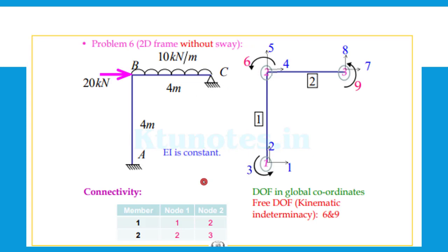Okay, so this will be the tedious part, because the local coordinate and the global coordinate are never the same, and for that you need a rotation matrix. So obviously for the beams, BC will have the local coordinate and the global coordinate the same, because there is no rotation required. It is actually theta equal to 0 degrees. But for the column, it is actually theta equal to 90 degrees. So those changes will be applied.